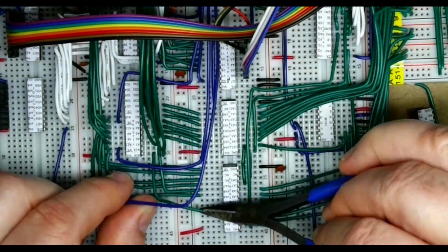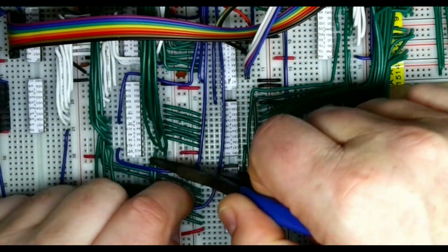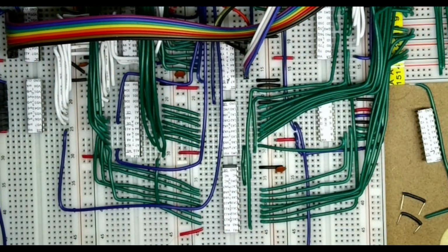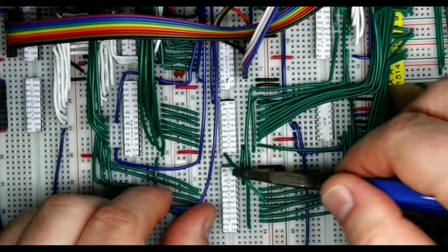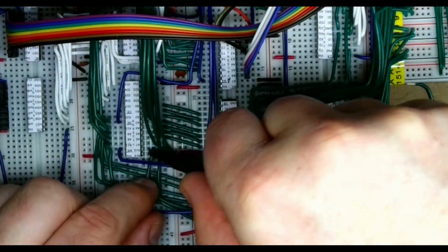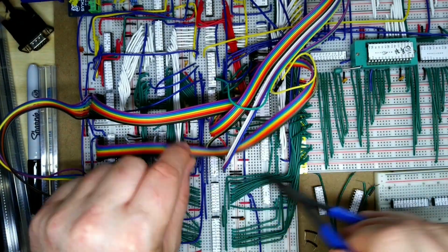So that's page address 0, page address 1 I think is already available there. And we just need to move the higher address lines down a little as well. I just need to put an extra wire in there because it's not quite long enough. So once all of those higher address lines are in, we're then just making sure the output enable's hooked in.